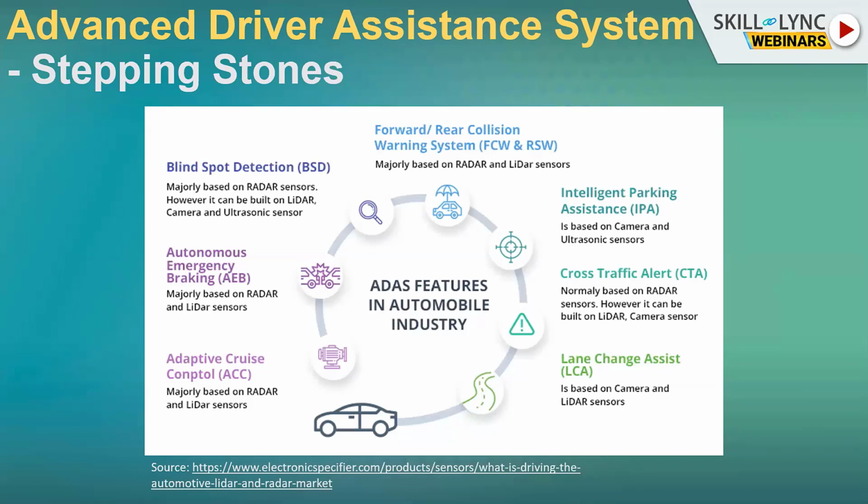So we have radar sensors, which monitor the blind spot zones of the vehicle. In case there is a car present in it and we turn on our turn indicators, the system starts warning us that it's not safe to make this lane change, because it has detected a car in the blind spot zone. Once this car is not present, you can continue to make the maneuver.